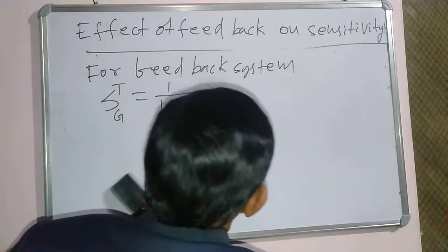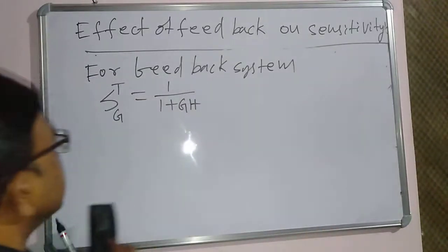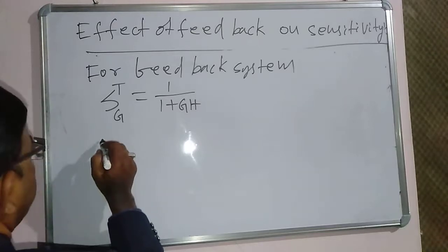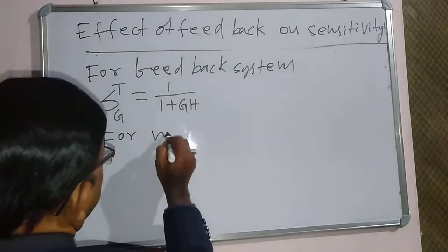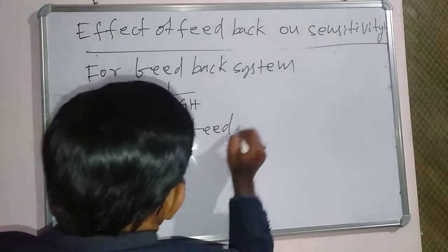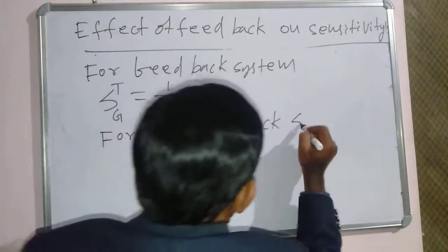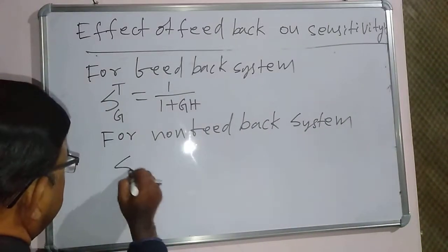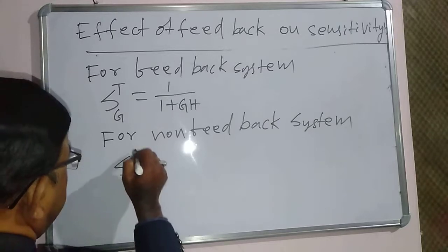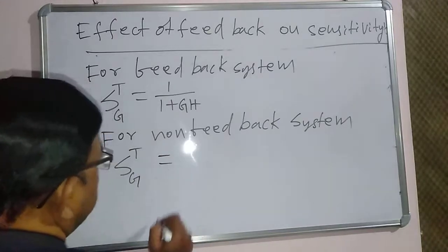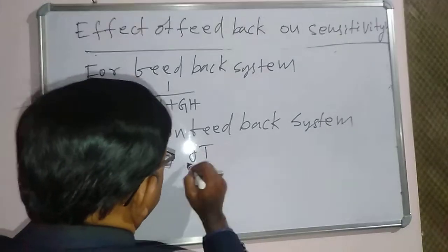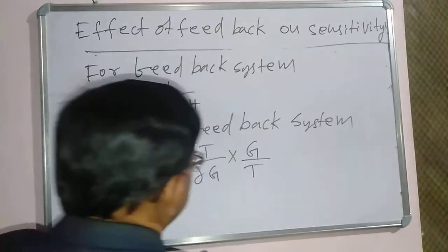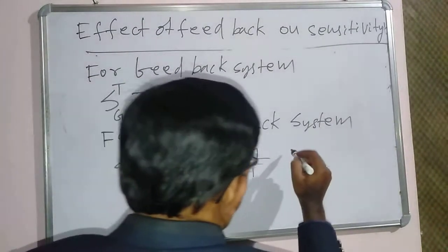Similarly, due to incremental change in G in a non-feedback system, the sensitivity is equal to ∂T/∂G into G/T.